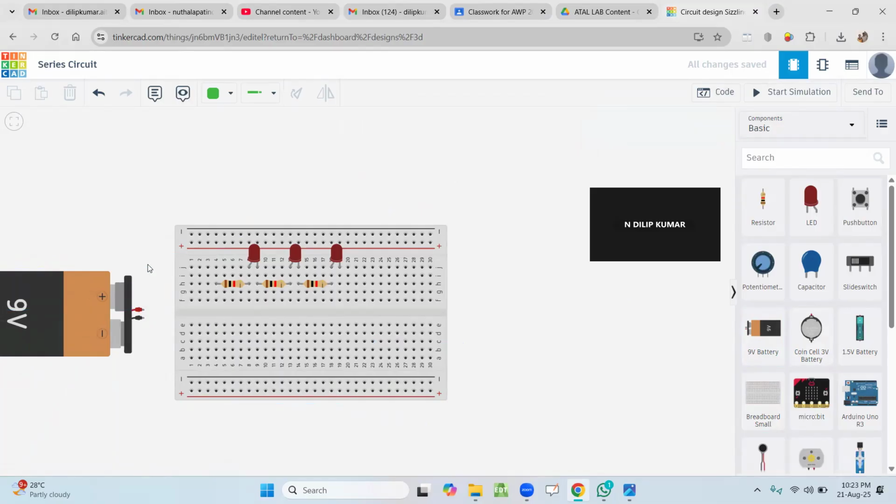In order to connect the battery, breadboard, LEDs and resistors, you need a wire. For that, place the mouse pointer on the positive terminal of the battery, click it and move the position, using vertical and horizontal motions only, as the wire should be linear in shape. There should not be any cross wiring. Connect here so that this horizontal rail is completely shorted with the positive supply.